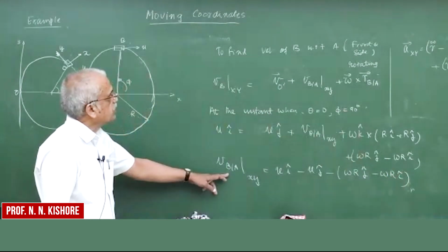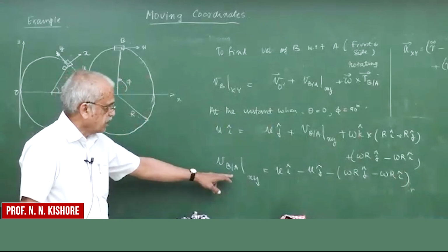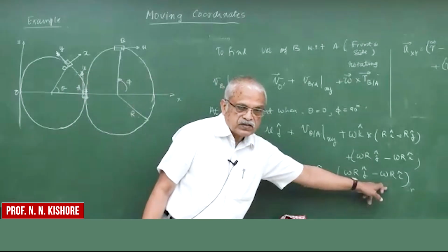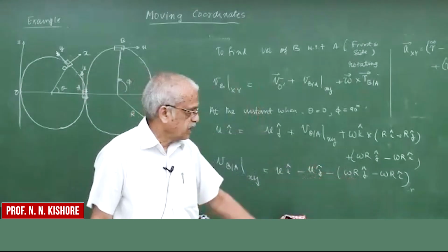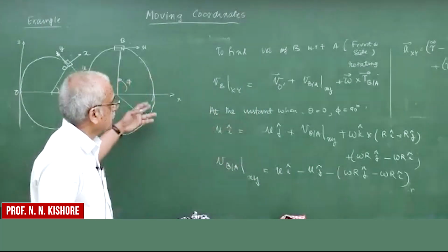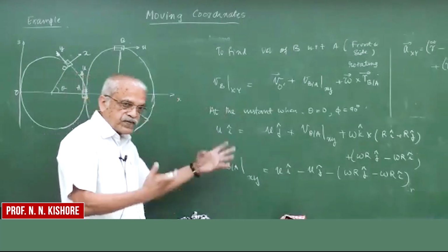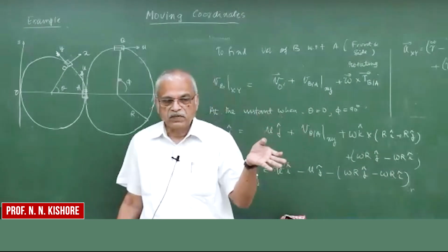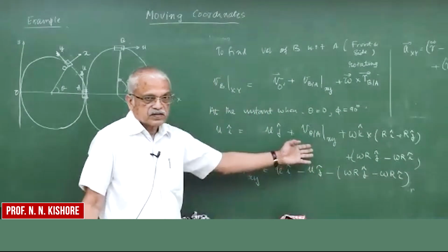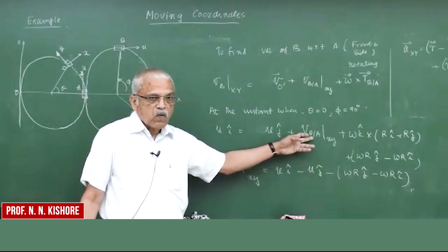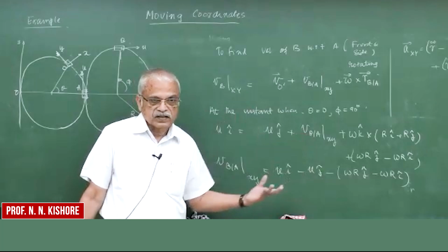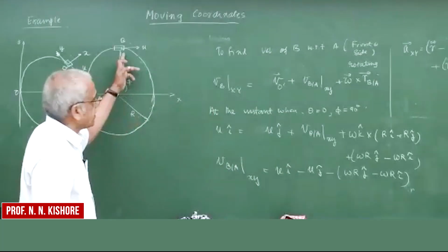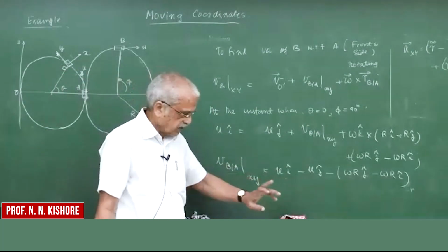Okay. So this is how to find the velocity of B as observed in the moving and rotating frame, given by this vectorial component form, right? This is how you can go from the fixed to the rotating frame. Not always from rotating frame observation to the fixed frame, but here some of them are fixed and we need to find out what will be. For example, if he has a radar fixed on this one, how it has to be rotated so that this can be tracked. That's how you can find out here. I think I'll stop here.